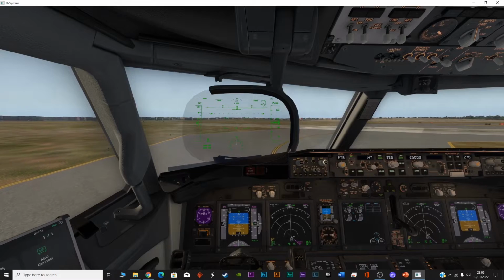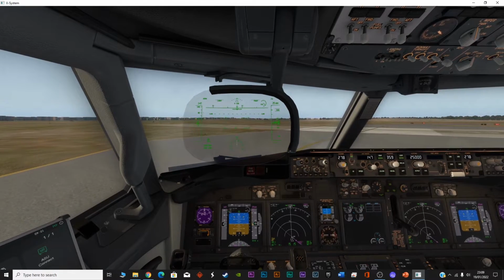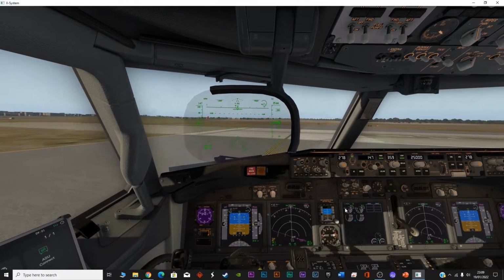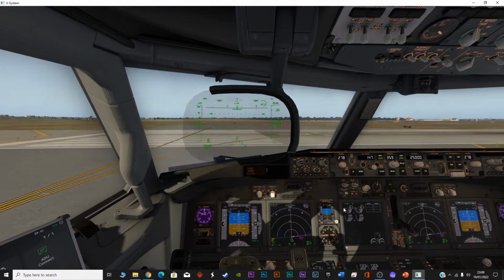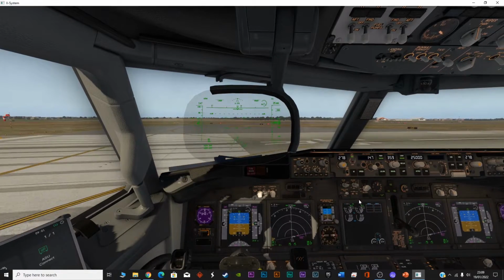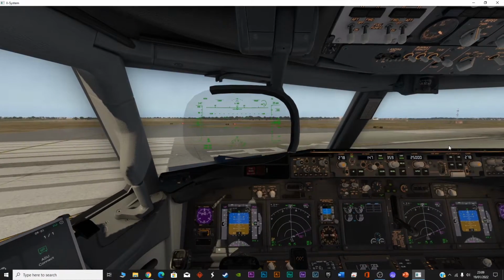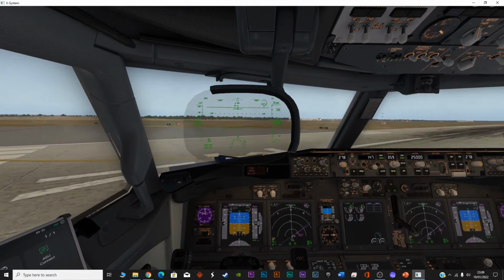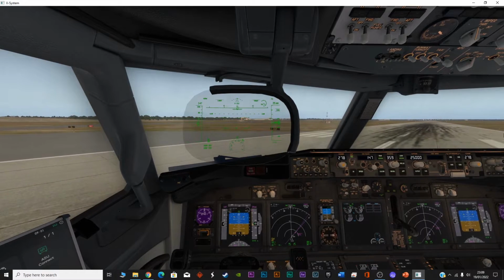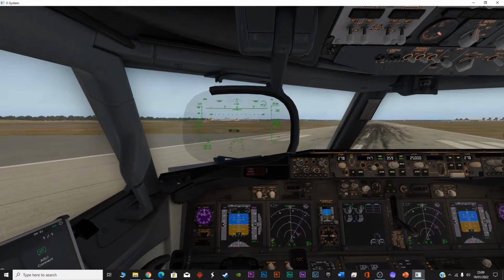Now I'm at the runway 36 right, and just look at this mark over here on the screen on the ECAM. You will see this green mark. We have to keep the throttle up to this mark. We'll not give 100% throttle, because we are keeping it at a deaccelerated rate, as said before in the takeoff settings.